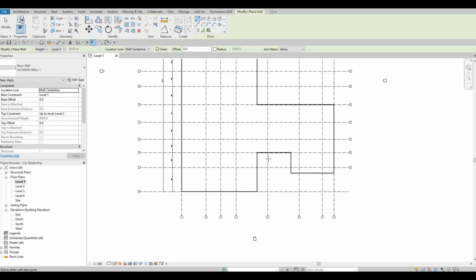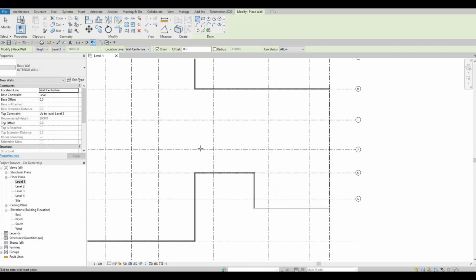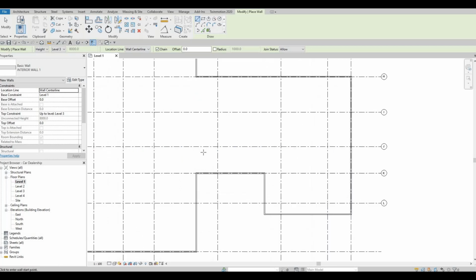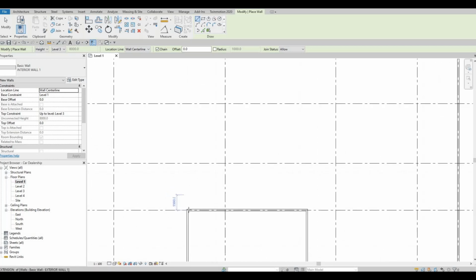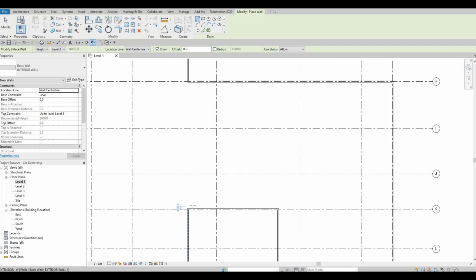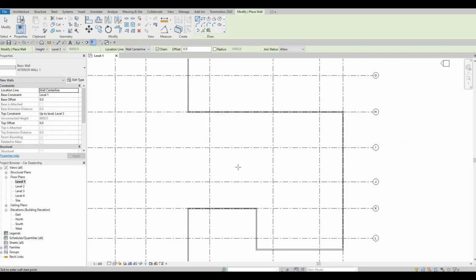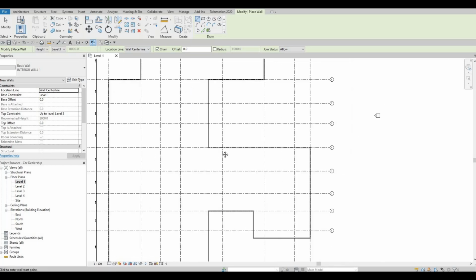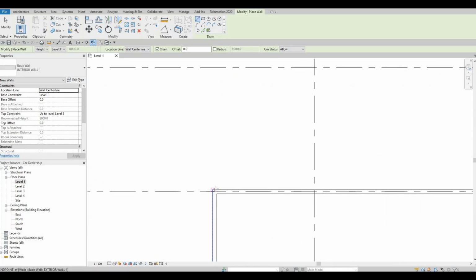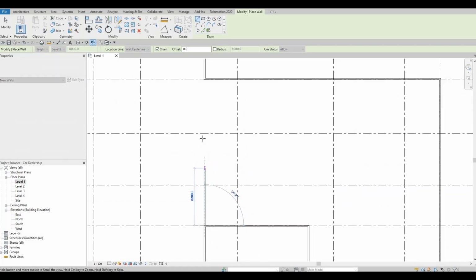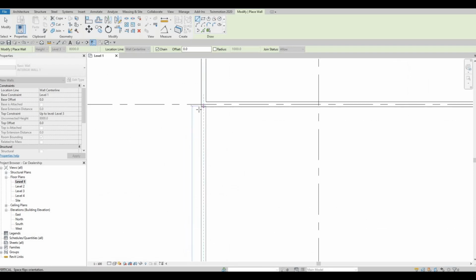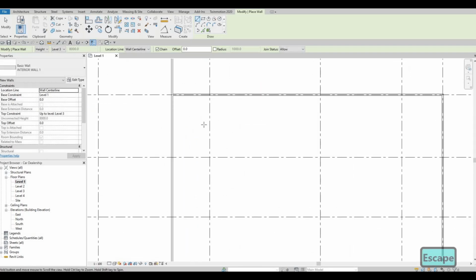So here we have our interior wall. Let's zoom in on this part. Like I said, this will be something that the car will enter here, service area, they're gonna be assessed, and then they're gonna be pulled out from here to the service bay 1 or 2. So here I'm just going to extend this. Luckily we're going to maintain the thickness of the wall to 200, so we don't need to align all of them, but it's easy to align.